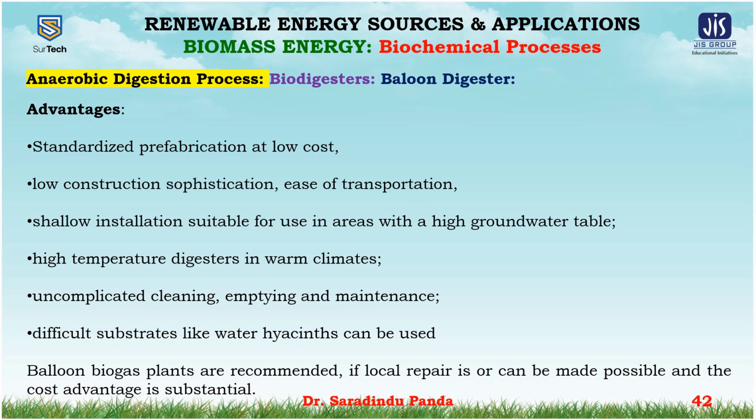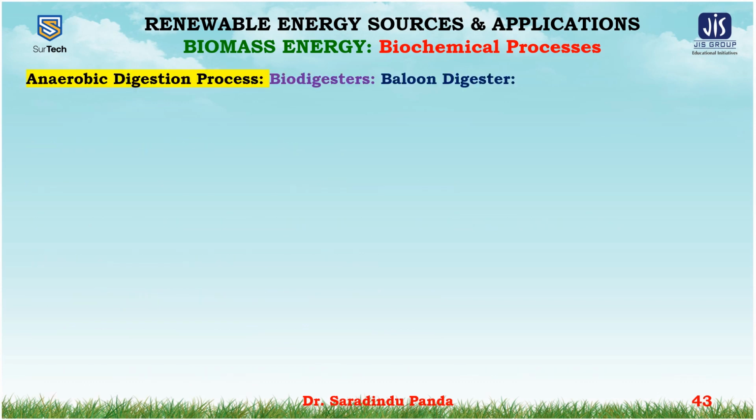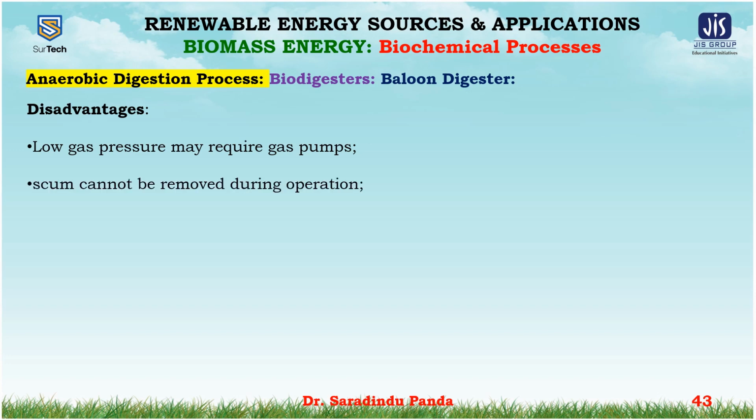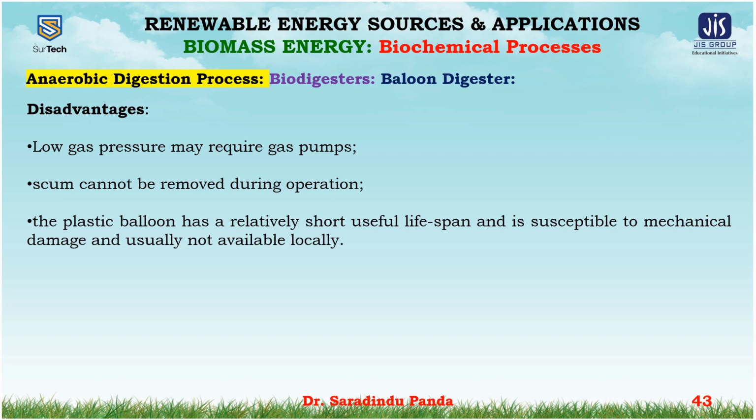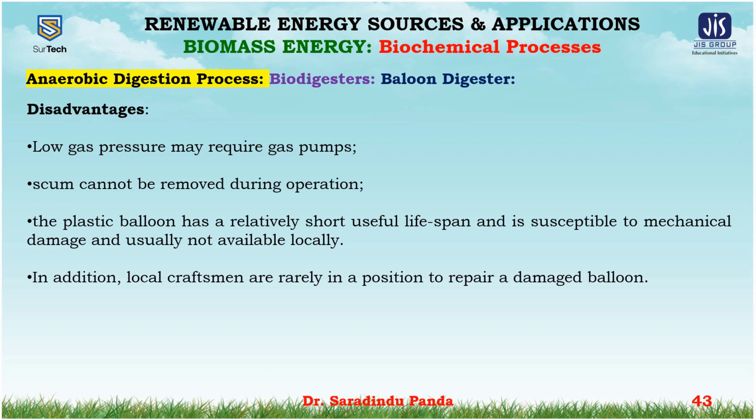Balloon biogas plants are recommended if local repair is or can be made possible and the cost advantage is substantial. The disadvantages of balloon digesters are: the low gas pressure may require gas pumps, scum cannot be removed during operation, the plastic balloon has a relatively short useful lifespan and is susceptible to mechanical damage, and it is usually not available locally.